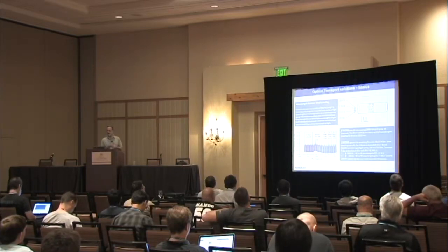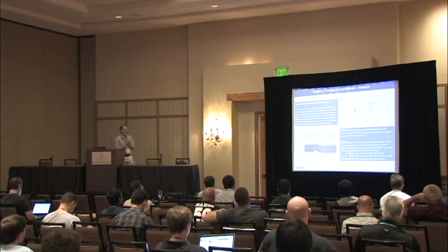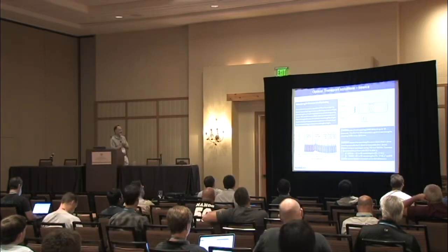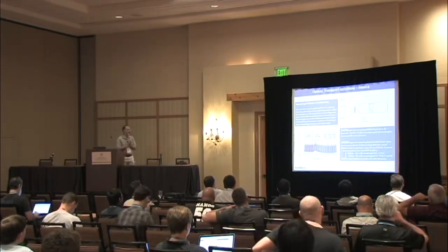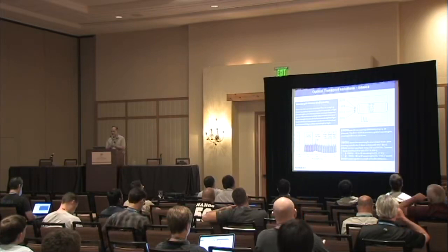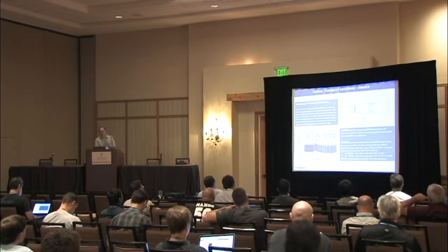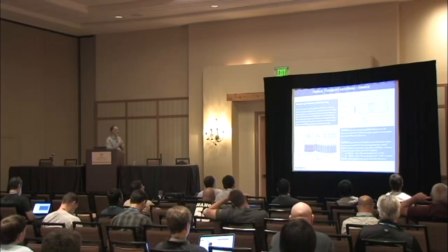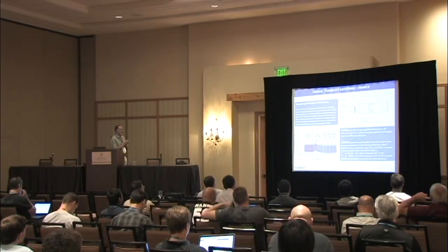You have in the industry two types of WDM, coarse wavelength division multiplexing using 20 nanometers spacing. And that defines per ITU standards 18 wavelengths in the range of 1270 to 1610. DWDM on the other side spaces more closely. I think the limit is 1.6 nanometer, covering typically the C-band and possibly the L-band.